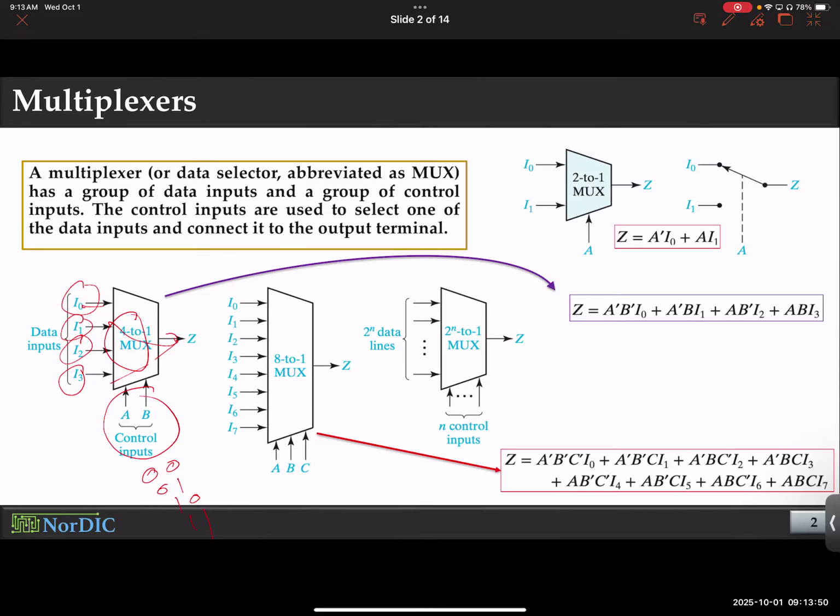and so on. Now, for some reason, if you need, say, 7 input rows, you still need 3 bits because there is no way for you to have anything between 2 and 3 bits, right? So you leave one of the combinations unused. That's okay. Now, there are ways to keep using the same mux, say 4 to 1, to make bigger ones. You can use multiple 4 to 1 muxes to make an 8 to 1 or 16 to 1 mux, or you could design a mux which is itself 8 to 1. For example, this is an example of an 8 to 1 mux. These are all block diagrams, so you don't see the difference, but when we actually implement the circuit, you'll see how that changes.